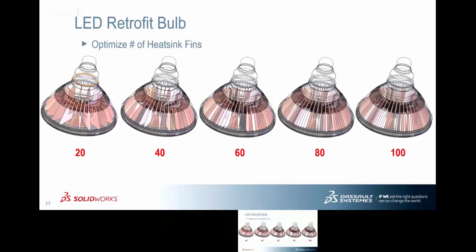So a question you might have when you're building this model is, how many fins would be best for that heat sink? We may think, obviously, the more fins, the better for cooling, but more fins might also be more expensive to manufacture. So really what you want to do is develop a heat sink in this type of application that has the least number of fins, the least amount of material, but can still effectively cool those LED chips while in service.